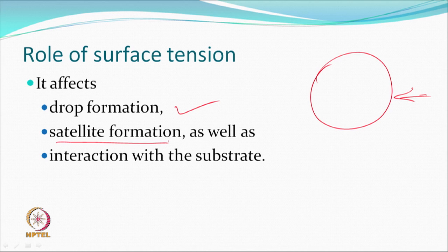and we want the dot to be a circle, a dot which is going to be created on a textile substrate. And you can appreciate that surface tension properties would determine whether the drop will very easily spread or it will just stay where it is before it is dried.